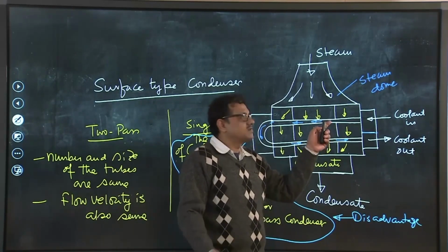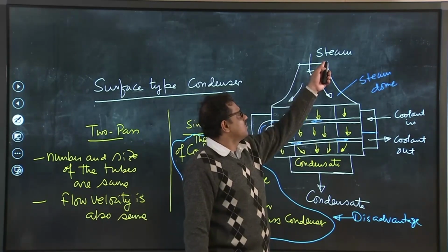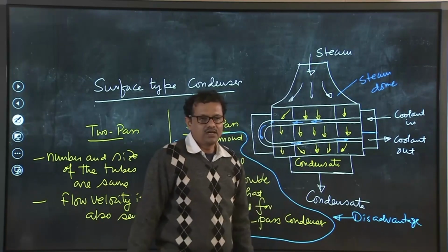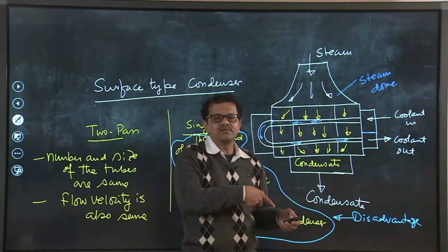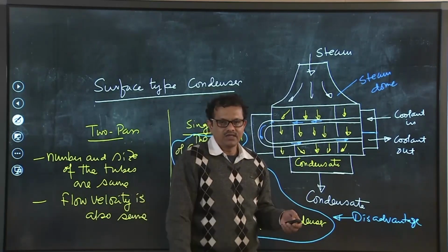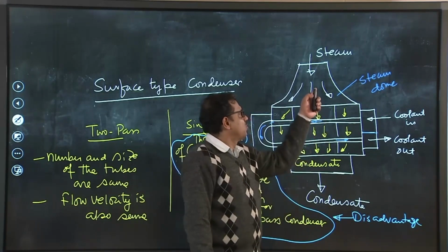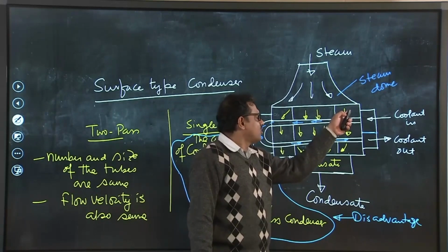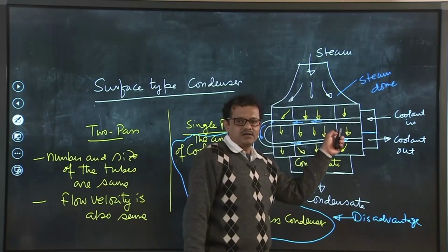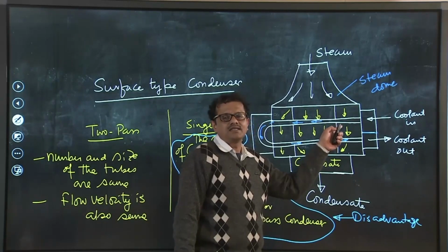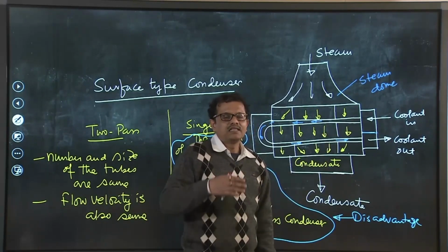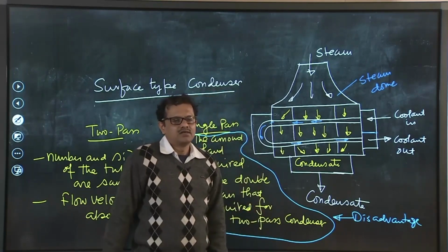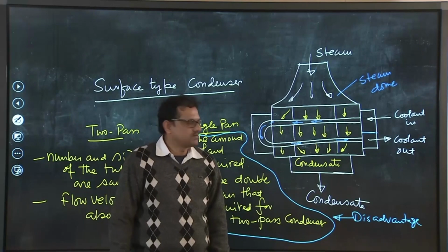Also, there is a possibility that when steam comes out from the turbine, that steam is having some amount of air which has already leaked into the steam through the turbine flanges. So, when steam is having air already, and also air will leak into the condenser, because condenser pressure is much less than the atmospheric pressure, that air will create two problematic issues.